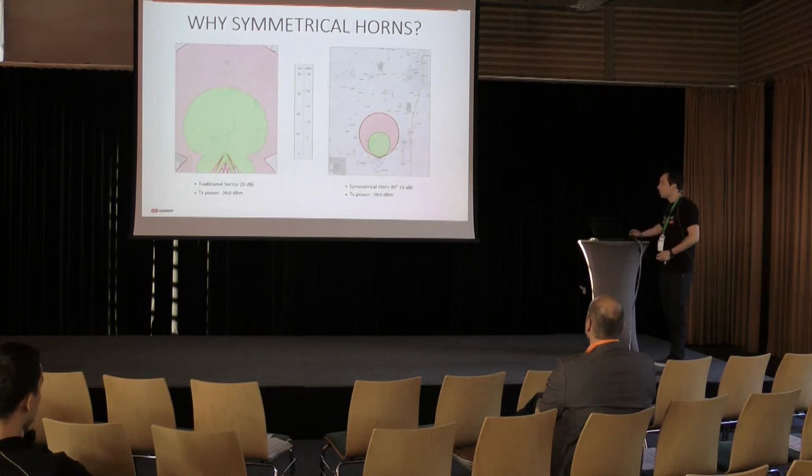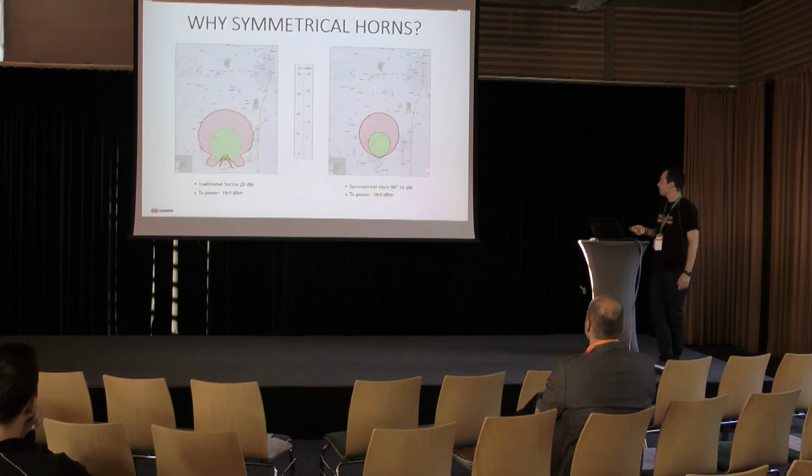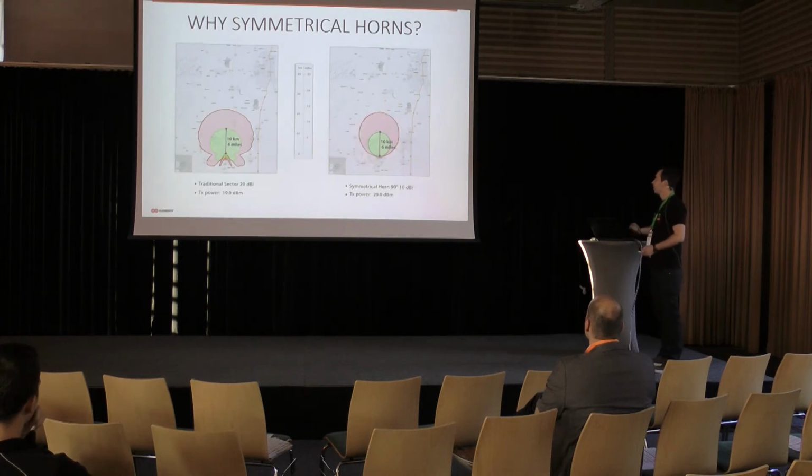So what's the solution actually is that you can increase TX power to the maximum on the antennas which are really made for that, but you will get the same result here with a 10 dBi antenna as you will get with 20 dBi. You will still connect clients at 10 kilometers, but you will miss these side lobes and back lobes. So your signal is really dedicated only to the place where you need it.